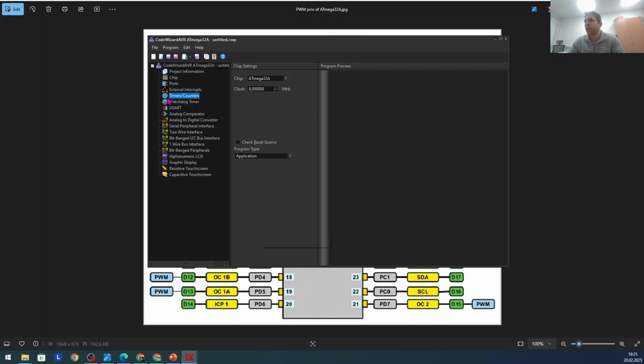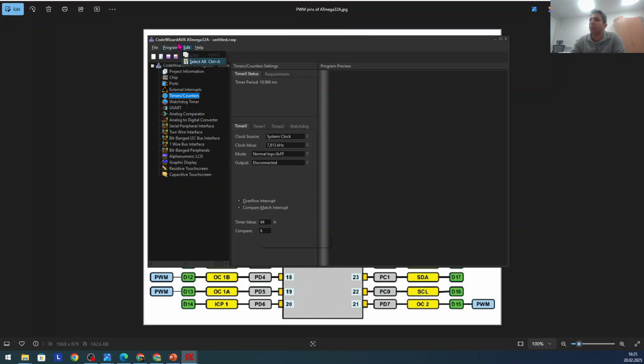This was the timer 0 setting. This 19 comes from here. If we wanted to use only timer 0 for the creation of the pulse width modulation, this would be it. I should go here and do program save. But I want to show how timer 1 also works. Timer 1 is also important. It is a 2-byte, 16-bit timer. So let's see how we set the period of the timer in this one.